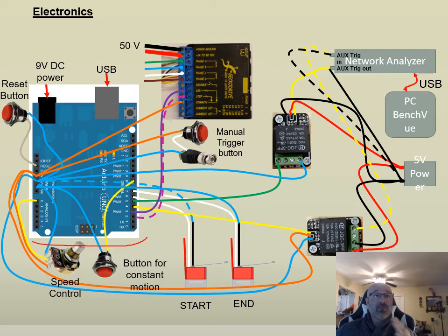We say go, it goes, and it reaches the end, it stops. So the only real thing in there is setting the time of, okay, at this time we start the motion, at this time we stop the motion, and from there we just know where it is based on the fact that it's a constant speed, which has its ups and downs, positives and negatives associated with it. With a system like that, it's really dependent upon the fact that you have constant motion. So any disturbances, any errors that are introduced in the system that cause that motion not to be constant, all of a sudden your position based on that constant motion and constant speed kind of go out the window.